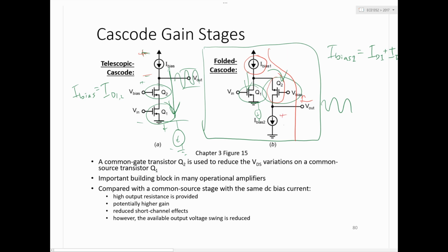You still need two NMOS transistors here, but on the left picture, you need 5, and on the right picture, you need only 4. So that buys you a couple hundred millivolts of extra swing, which is precious if you've only got a 1 volt total power supply.